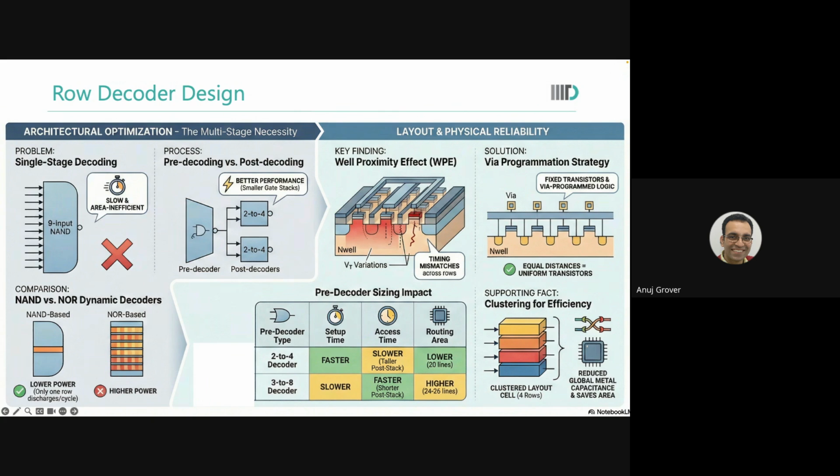Now, what about dynamic? For the dynamic gates, even in the pre-decoding stage, you will have a clock interacting with the addresses. So how many gate stages do you have before the clock arrives? Just a few buffer stages and a latch.